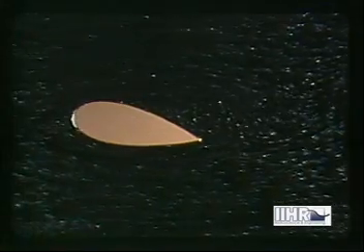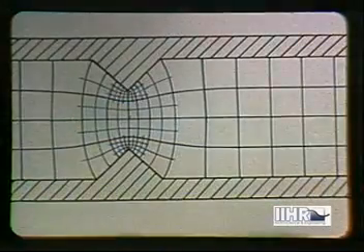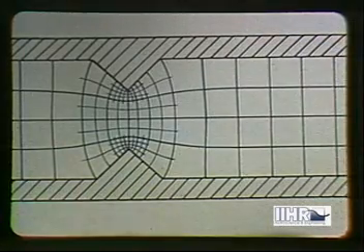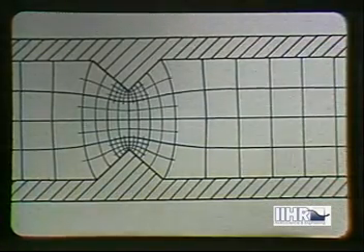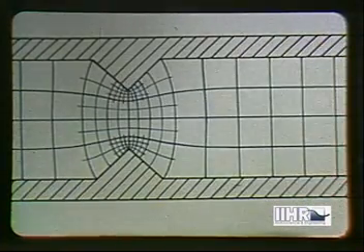A type of separation which is of interest now is that due to boundary angularity. The flow net for a sharp boundary angle would call for an infinite velocity at the corner, which is physically impossible.